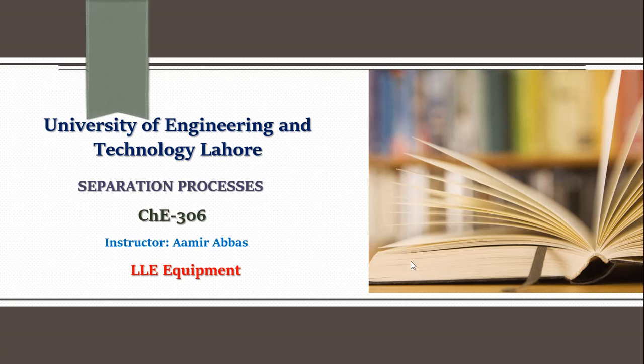So yesterday initially I talked about liquid extraction, the technique which involves extraction of a component of a liquid which is a feed. Actually in our feed there is more than one component, and you want to extract one of those components from that liquid with the help of an externally introduced solvent in the form of a liquid. So in this technique we remove some specific components from the feed which are desired, which we want to separate. The external liquid or solvent you introduce will extract some of the components of the feed, while other components will stay as such in the feed.